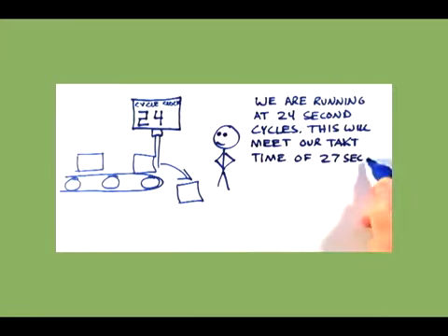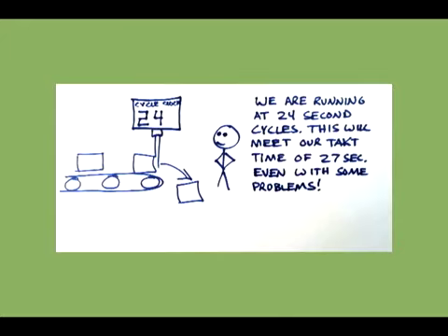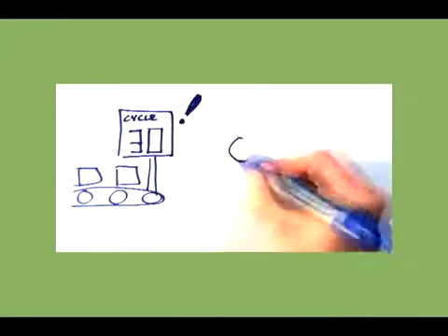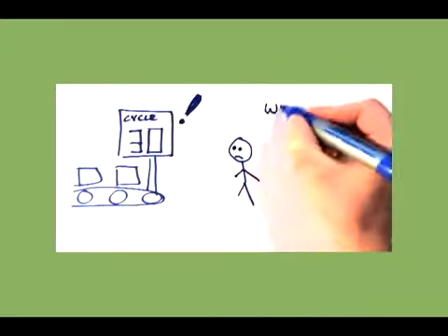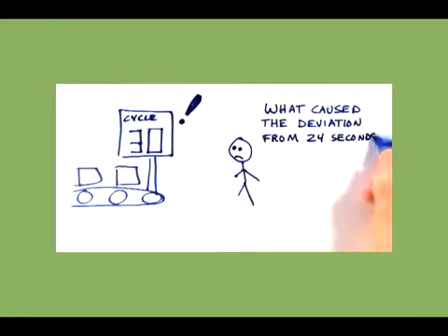You can continue to measure those cycles, output, output, output, and so on, to determine how reliably your process is able to meet its cycle time. Producing at a consistent and predictable cycle time indicates a stable process and allows you to see abnormalities quickly.